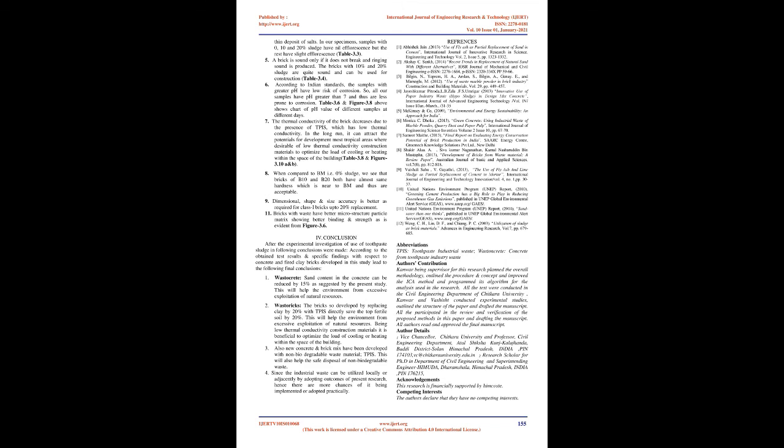For conclusion. After the experimental investigation of use of toothpaste sludge, the following conclusions were made. According to the obtained test results and specific findings with respect to concrete and fired clay bricks developed in this study, we reach the following final conclusions. 1. In Wastocrete, sand content in the concrete can be reduced by 15% as suggested by the present study.